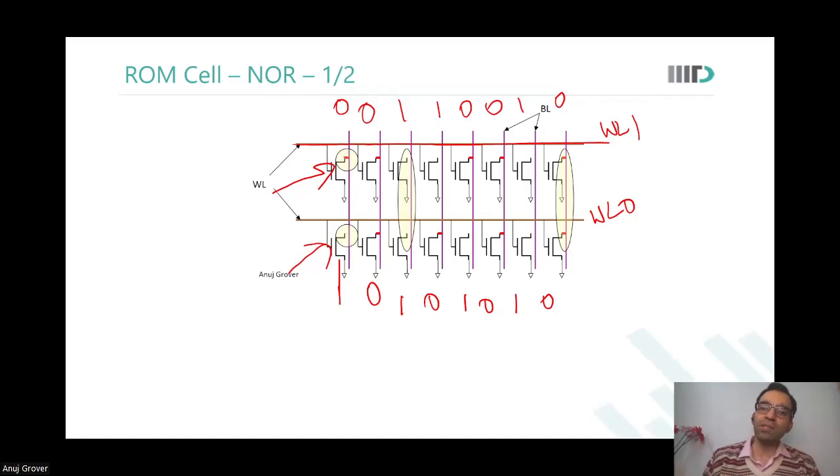Now the problem is that over here every bit line has different capacitance. So how will you size your pre-charge circuit? How will you size your write driver circuit? There is no write driver in a ROM, but pre-charge is there. So some columns will get pre-charged very fast, others will not get pre-charged fast. Some columns will discharge very fast, others will not discharge fast.